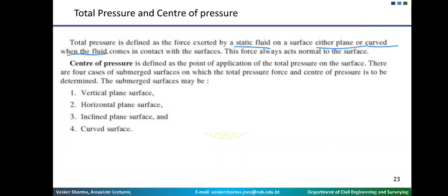Those forces will always act normal to the surface, and that force is known as your total pressure. Then, at what point does this net force act on that surface? Since it acts on all the points, where is the point of application? That point of application is known as your center of pressure. Basically, center of pressure is at what particular depth the force is exerted.